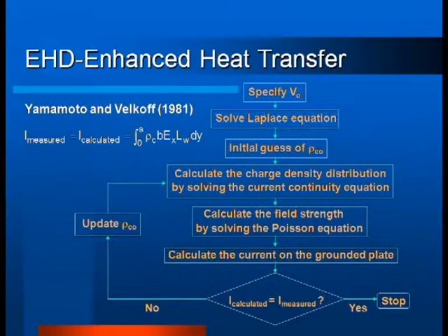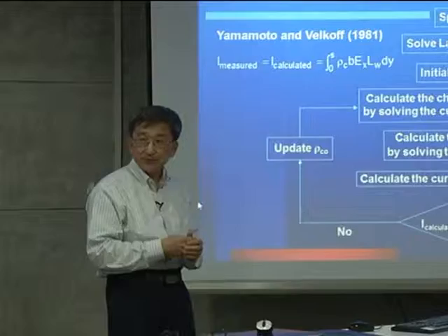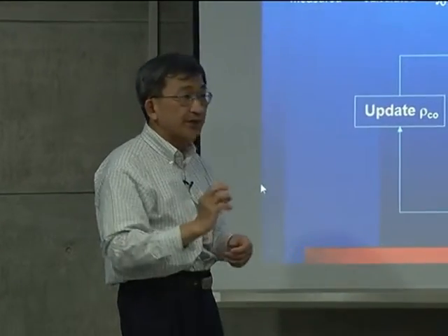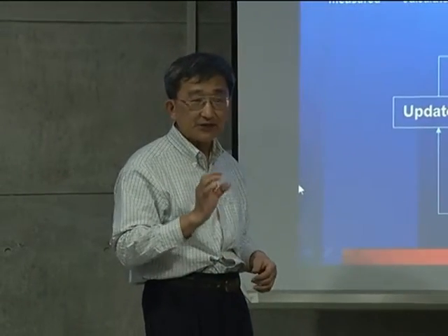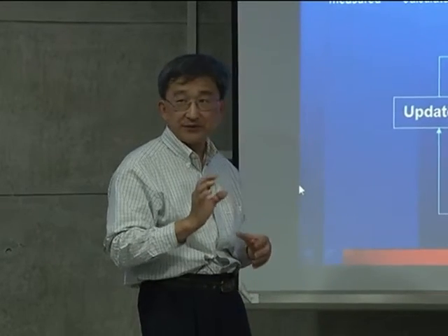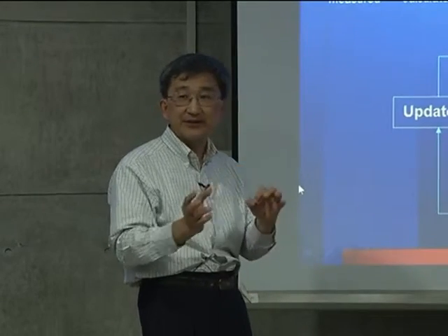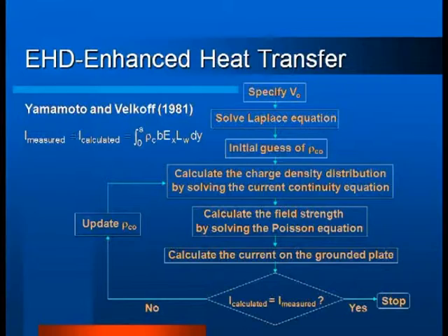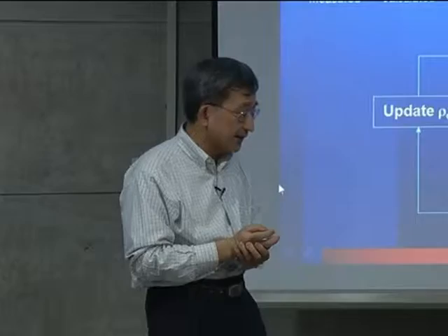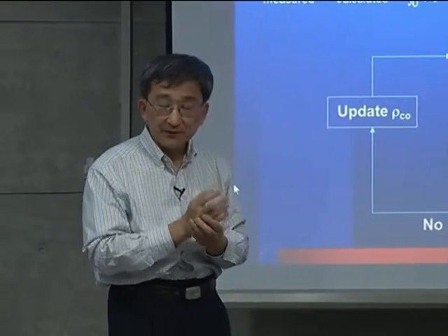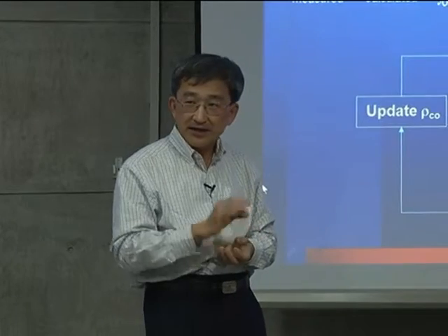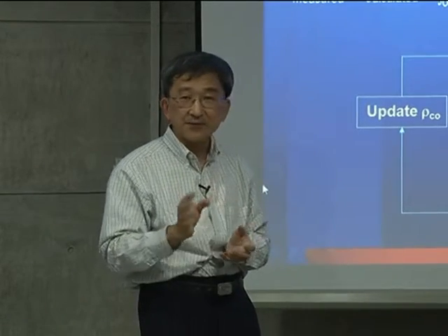Because the electrical body force will come into play, as the charged particles are going to drive the fluid, we need to calculate this electrical body force accurately. If we don't calculate it accurately, then your flow field and temperature field calculations will be all wrong. Some of you may have used Fluent, or some of you may use COMSOL, all these commercial packages.